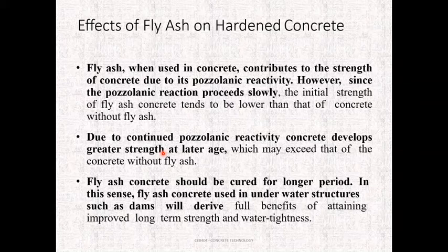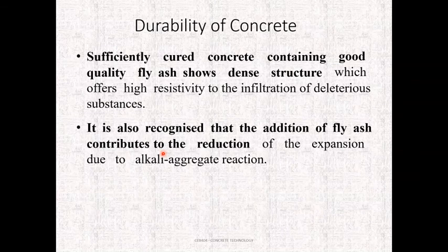In this case, fly ash concrete can be used in underwater structures such as dams, which will derive the full benefit of attaining improved long-term strength and water tightness. Durability of the concrete. Since sufficiently cured concrete containing a good amount of fly ash shows a dense structure, it has a high resistance to the infiltration of deleterious materials.